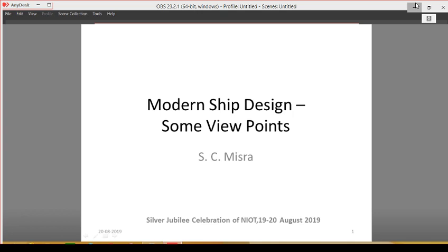I was really amazed. This is something we have been talking about. Can we standardize? Can we rationalize designs? So that we can have a number of ships coming out of a modularized concept of ships, ship hull as a whole module or ship hull as a part module, and fixing different things, and we get different ships, different platforms. And with regard to that, we have done some work at IIT Kharagpur and later at IMU Vizag. I'll just give you one example. You can see the front end of the ship. There are 2 different bulbs which have been fitted in the front part.